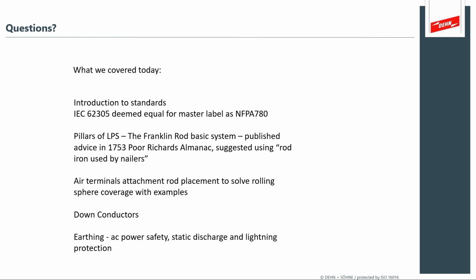So when we bring a down conductor past those elements, the rain gutters, that type of thin walled construction material, we want to bond to it. So you could hold it away half a meter or bond it. So it's back to what's the building structure look like, and what are you capable of?